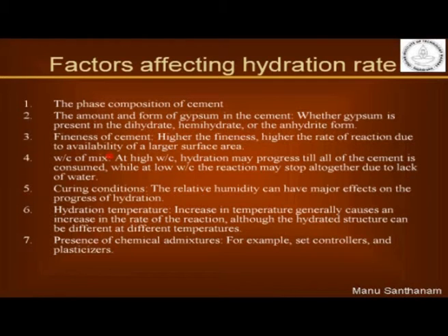Water cement ratio of the mix. Now I told you already about the rate of reaction with respect to water cement ratio. At low water cement ratio, your rate of reaction is much faster, but nevertheless at high water cement ratio, your water content is so high that your hydration may proceed for a very long time, because you have a lot of water available in the system. Curing condition, of course, if you have very drying condition, you will not have any water present to hydrate the cement, it will start drying out. So that is why we need to provide curing to ensure that water has the chance to react with the cement to produce the hydrated skeleton, which is responsible for low porosity and permeability in the system.